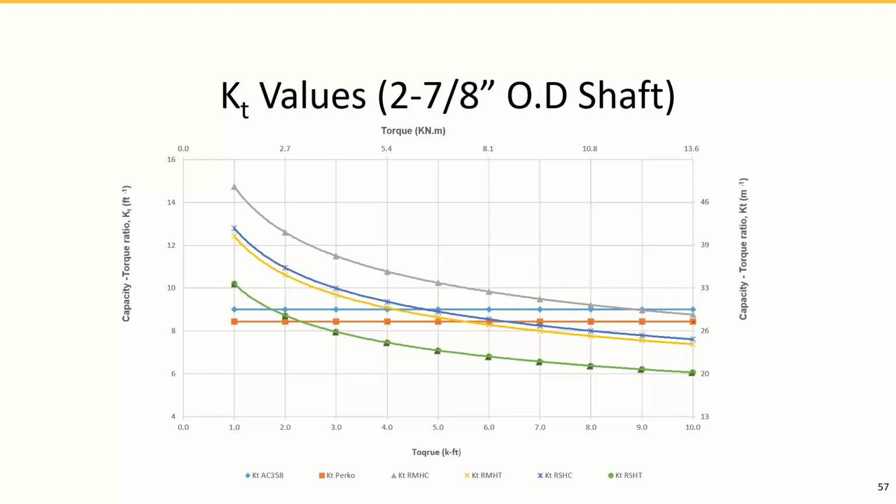There is some disturbance of the soil, and that's why in tension, when you pull on it, that soil is disturbed. Plus, if you look at that equation from when we use the envelope bearing plate method, where Q is equal to A multiplied by AH multiplied by cNc plus qNq plus 0.5 gamma D N gamma, that 0.5 gamma D N gamma is the compression term that exists in compression. But in tension, it doesn't exist, even though that small capacity is still there. So that's why we have less in tension than in compression. And based on the test results, I've seen it depends. It really varies between 10% to 15 or 20% less than in compression.